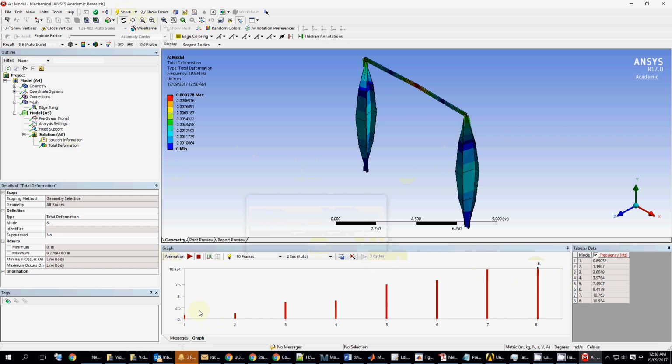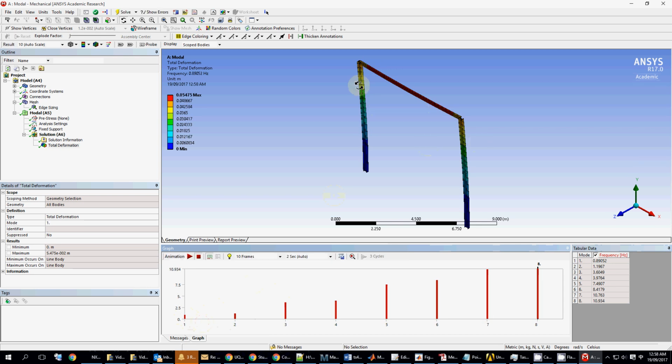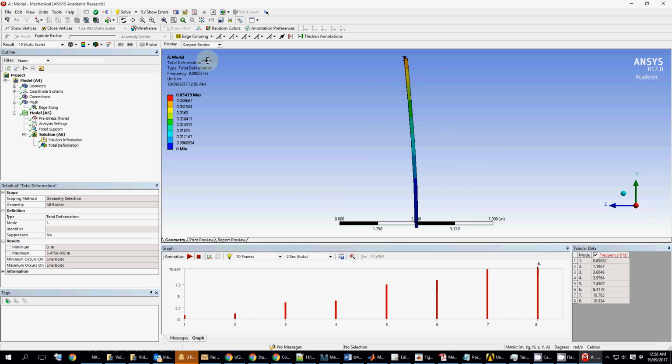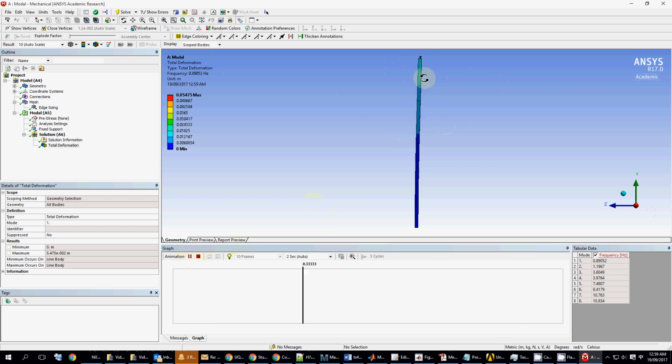From this graph, you see we have found 8 natural frequencies, 1, 2, 3, 4, 5, and the frequency in hertz is plotted in this table. To see the mode shape, you just need to click each of the modes and retrieve this result. So this gives you a mode shape, and to give you a bit better plot, you can see the mode shape is actually that way. If there's animation, you can plot. So that's the vibration mode shape. It's actually an out of plane mode.